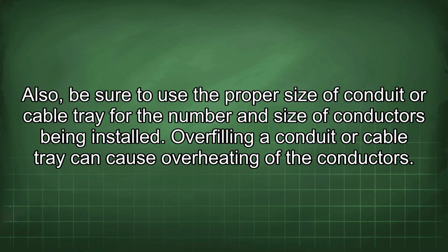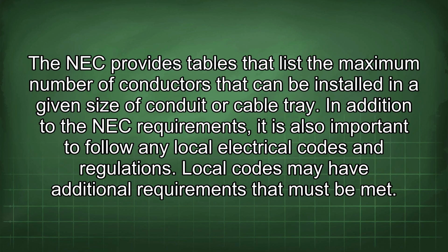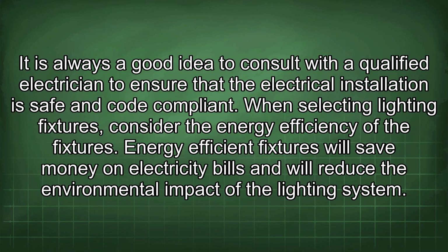Also, be sure to use the proper size of conduit or cable tray for the number and size of conductors being installed. Overfilling a conduit or cable tray can cause overheating of the conductors. The NEC provides tables that list the maximum number of conductors that can be installed in a given size of conduit or cable tray. In addition to the NEC requirements, it is also important to follow any local electrical codes and regulations. Local codes may have additional requirements that must be met. It is always a good idea to consult with a qualified electrician to ensure that the electrical installation is safe and code compliant.